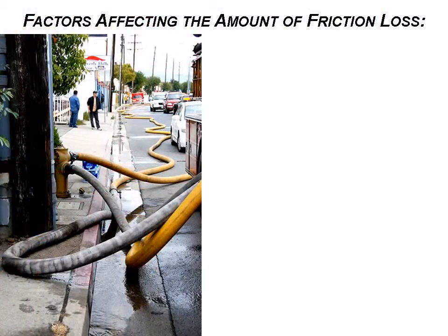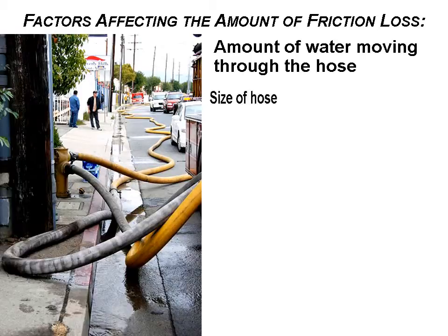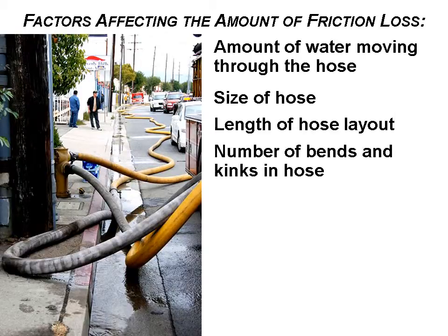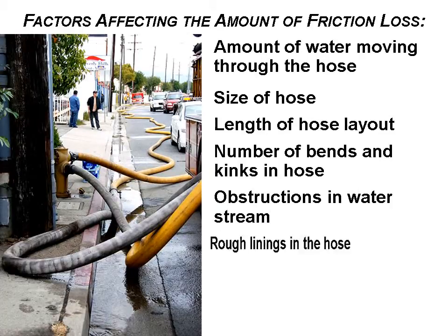Factors which affect the amount of friction loss: the amount of water moving through a hose, size of hose, length of the hose layout, number of bends and kinks in the hose, obstructions in water streams, rough lining in the hose, more adapters than necessary, and damaged couplings.